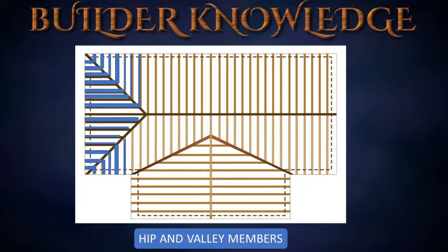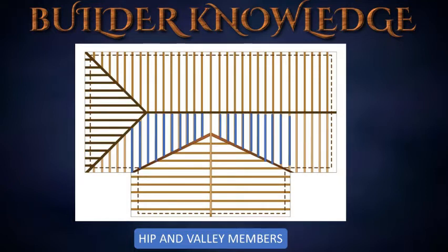Hip jack rafters: their lower ends rest on the top plate, and the upper ends rest against the hip rafters. Valley jack rafters: their lower ends rest against the valley rafters, and the upper ends rest against the ridge board. Cripple jack rafters are nailed between hip and valley rafters and do not touch the ridge or top plate. King common rafters extend from the ends of the ridge board to the top plate. Side king common rafters extend from the ends of the ridge board at a 90-degree angle.